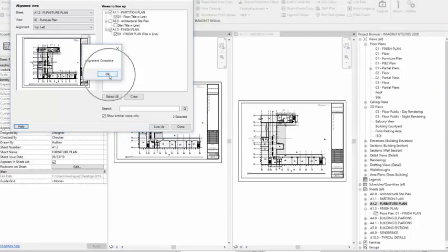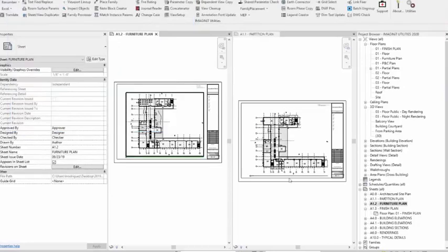It will give us a message that it has aligned those views, and then you watch that view right there. When I go to hit done, that has now moved to align with this view right here. So we just did one sheet here, but if you had hundreds of sheets, it will work just the same. One thing to note is that with the Viewport lineup, it does use the crop region for aligning, so they do have to be the same size and location in all of the different views that we are aligning. Okay. So that is a Viewport lineup.